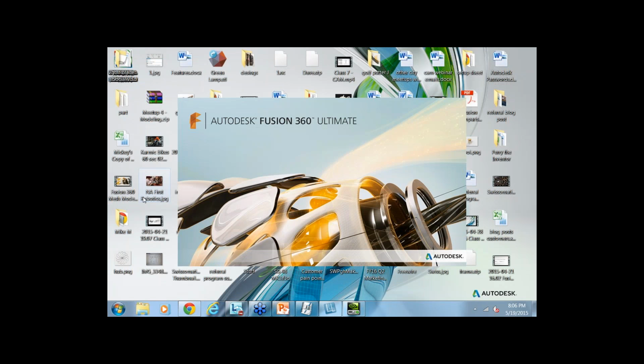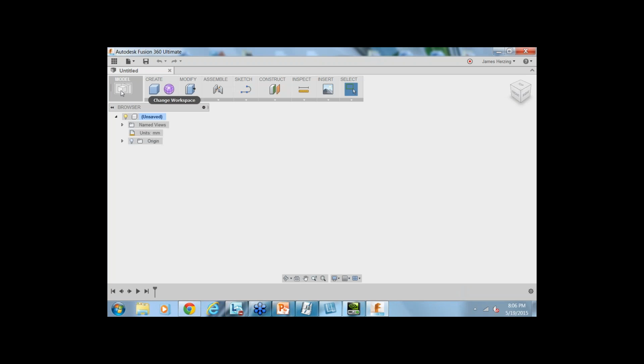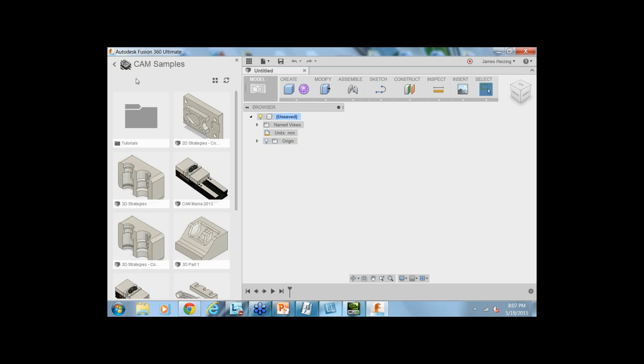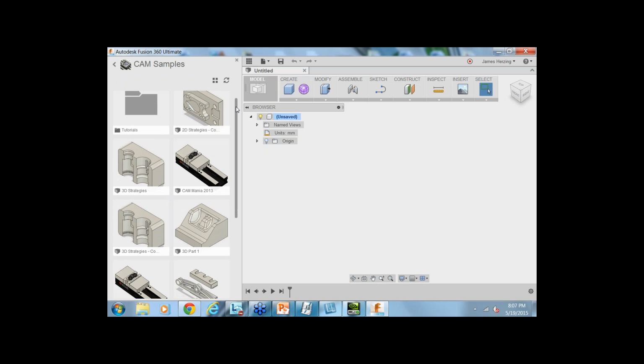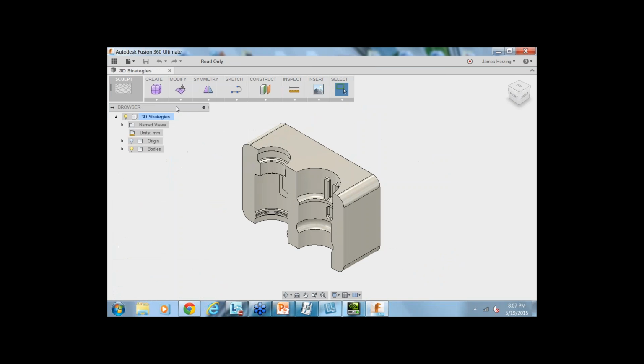Those operations were to set the origin? Yep, set the origin in that bottom left corner so that the z-axis is pointing at you. Got it. And then when you're in stock, use a relative size box. There it is. Look how happy it is. So I'll go through the steps for you right now.